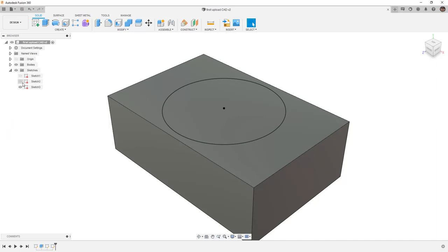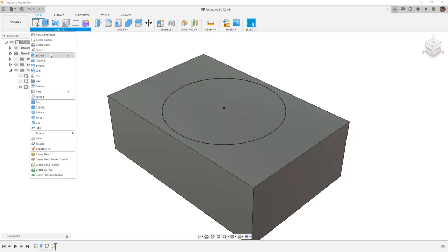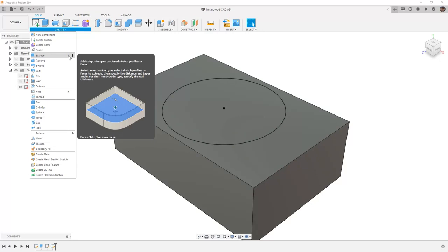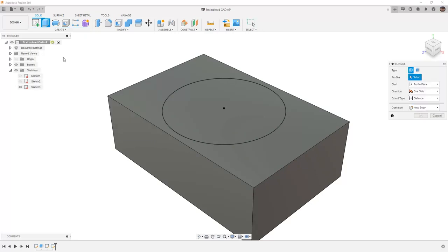We've already created 2 sketches in this design, and we now want to explore creating solid geometry from them. So the first thing that we want to explore is using sketch 3, which was our center diameter circle, to create an extrude. In order to do this, we're going to go to the Create menu and select Extrude, or use the shortcut E on the keyboard.